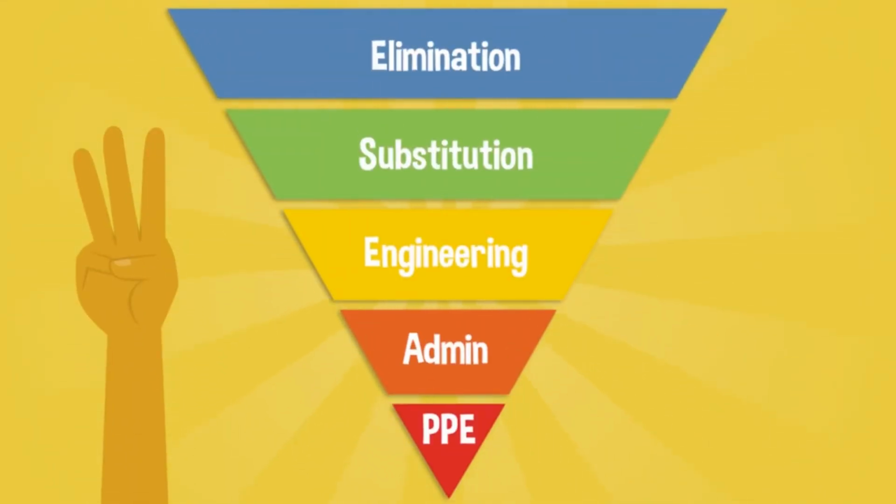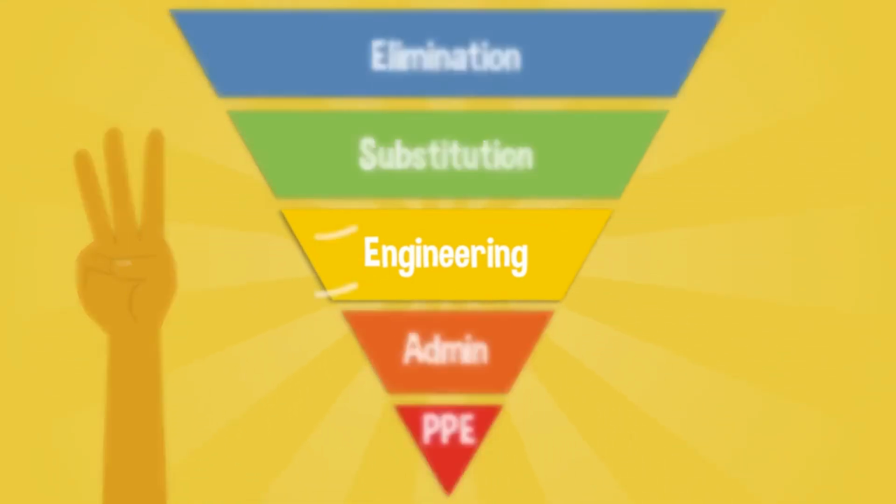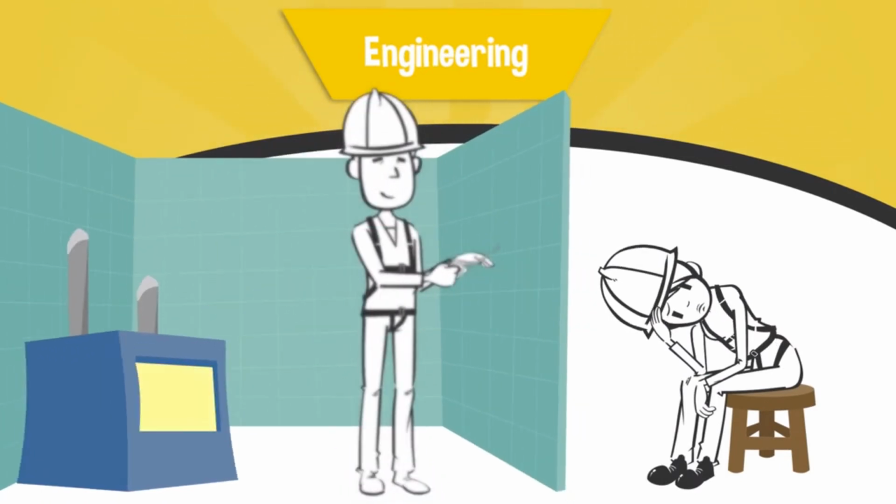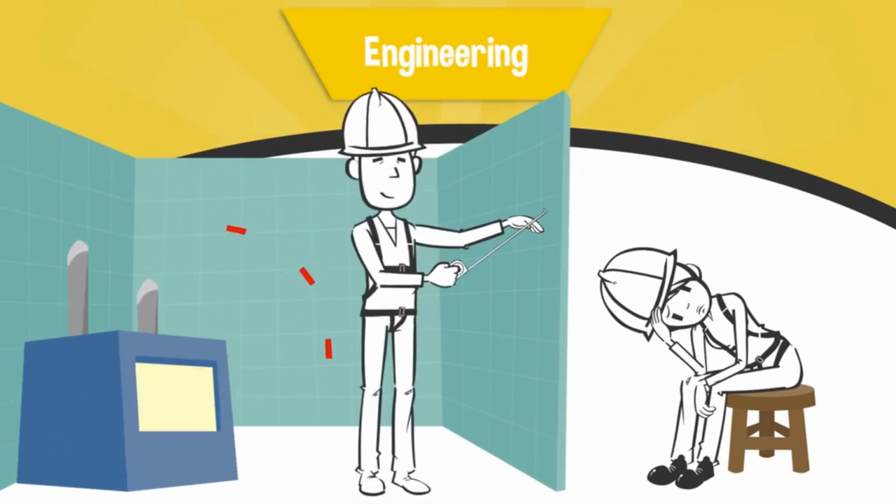When substitution is not possible, the third most efficient way to protect yourself from hazards is to implement a technical control, i.e., a system that will help you isolate the source of a hazard. This is what we call the engineering controls of hazards. They include the modification of equipment, the manufacturing of additional parts, the implementation of control technologies, in fact, any addition of material or technology to control the hazard. This could be, for example, machine enclosure, or adding acoustic barriers to limit the impact of noise annoyance on your hearing health.